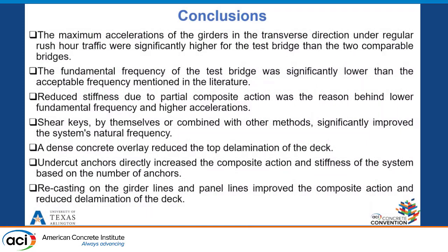And finally, the conclusions. The maximum accelerations of the girders in the transverse direction under regular rush hour traffic were significantly higher for the test bridge than the other two comparable bridges. The fundamental frequency of the test bridge was significantly lower than the acceptable frequency mentioned in the literature. The reduced stiffness due to partial composite action was the reason behind lower fundamental frequencies and higher accelerations.